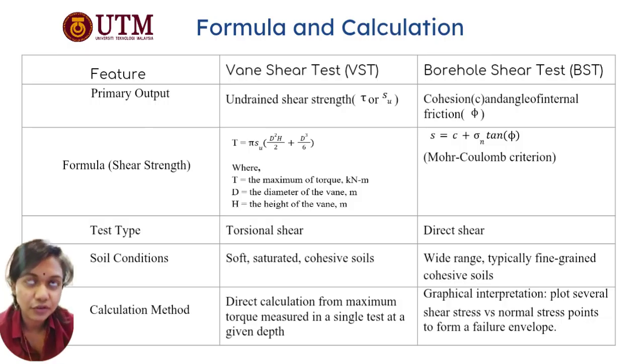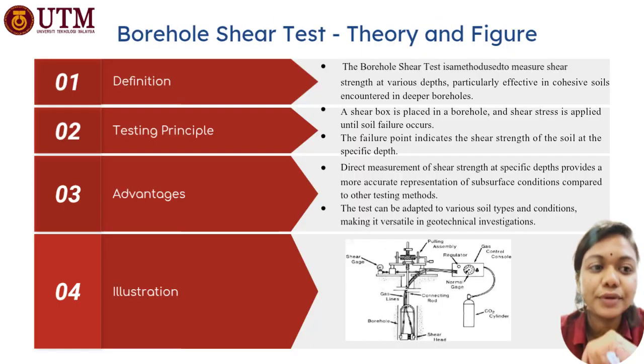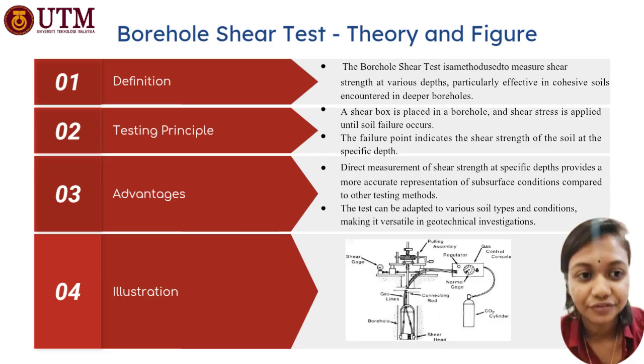VST is the Vane shear test, which gives quick undrained strength at specific depths, while BST is the Borehole shear test, which provides a more complete shear strength profile.